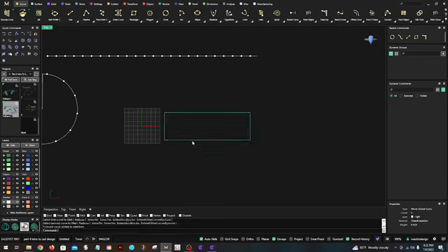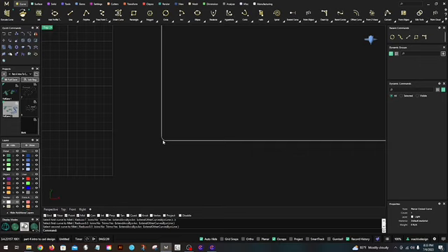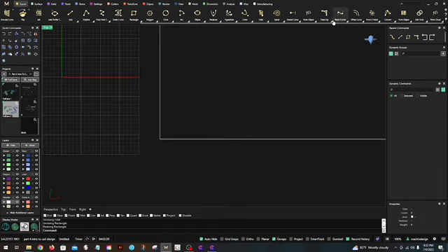All right, I brought this rectangle in, and let's go up to cleanup, fillet curves, and select first curve to fillet. Oh yeah, and the radius is 1. So this would be the time to put in like 0.5. All right, I think. Oh yeah, see that? It's so tiny. I'm going to back up and do a larger radius. Oops, backed up too far. Okay, so I'm going to fillet the corners.